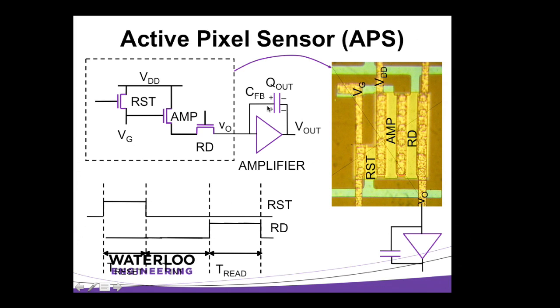You can use very simple physics, Q is equal to VC, to figure out the relationship between the charge on the output and the charge on the input. And the key factor controlling that relationship is time. The longer you integrate, or the longer you leave this capacitor charging, the larger signal you get. So your charge gain is a function of your sampling time. That was the neat way. You just integrate the signal for a while, and you get a pretty good signal out of it. That's your charge gain. This was one of the first active pixels that we built in amorphous silicon.